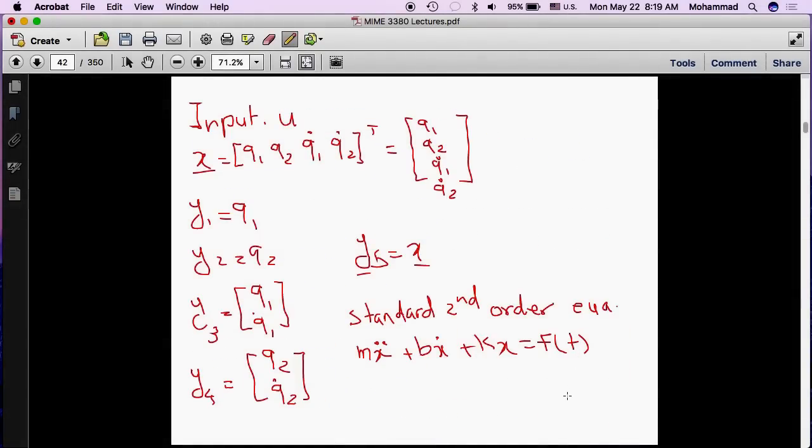So if you have a system that looks like this, a mass here attached to a spring and attached to a damper, and its motion is defined with variable x of t, and there is an external force F of t applied, and the stiffness is K, the damping coefficient is B, your differential equation essentially looks like m x double dot plus b x dot plus k x. Where do we get that? How do we arrive at this differential equation?